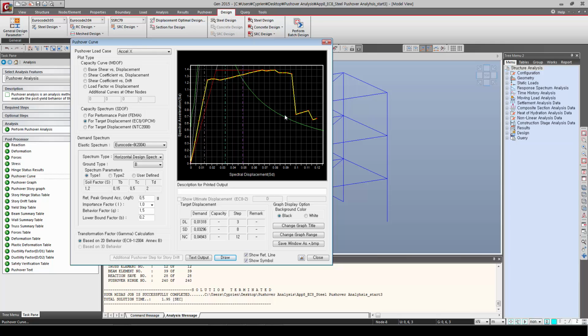For the detailed formula of the target displacement, refer to Annex B, determination of the target displacement for nonlinear static pushover analysis. The target displacement obtained from the above corresponds to the seismic demands of the limit state of significant damage. The target displacement of the limit state of near collapse is taken equal to that of the SD multiplied by 1.5. The target displacement of the limit state of damage limitation is taken equal to that of SD divided by 2.5.